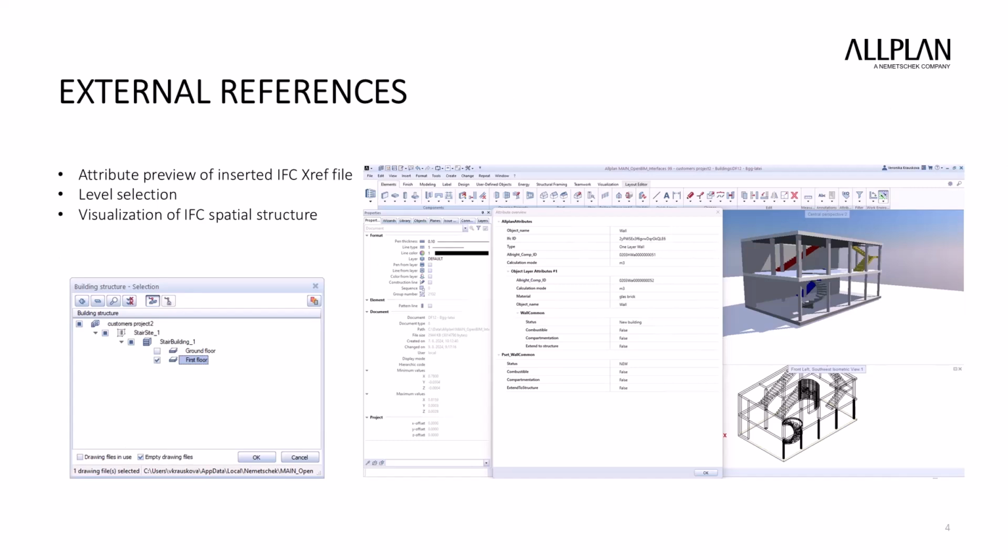Xref Manager is, as I said, a completely new tool, but of course we didn't forget about the already existing ones. We also save time with IFC Xrefs, which now has an option to view attributes directly in Allplan. So there is no need to open an extra window with the viewer for checking element properties.